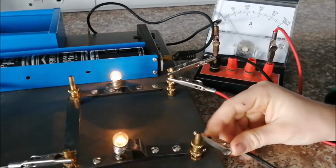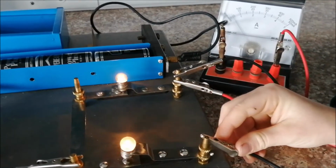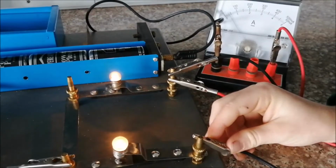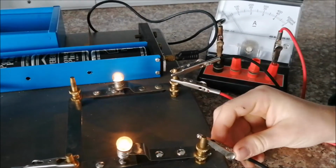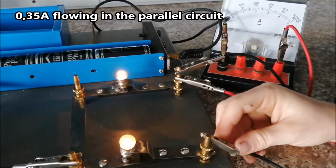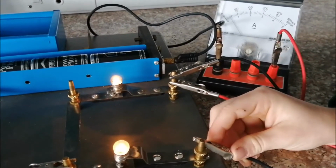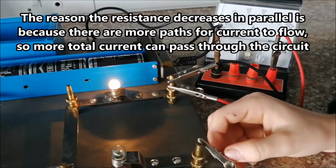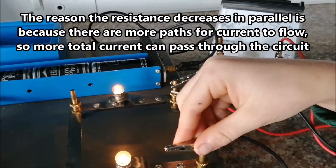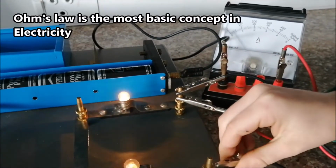Reconnect the circuit so that we have a parallel circuit. What we are effectively doing there, and you'll learn a little bit about this, is decreasing the total resistance of the circuit. Because we are decreasing the resistance, the current goes up to about 0.35 of an amp. That is what we're getting on the ammeter. So as we decrease the resistance, we increase the current, because that's the relationship between those two variables according to Ohm's law, which you will learn about later.